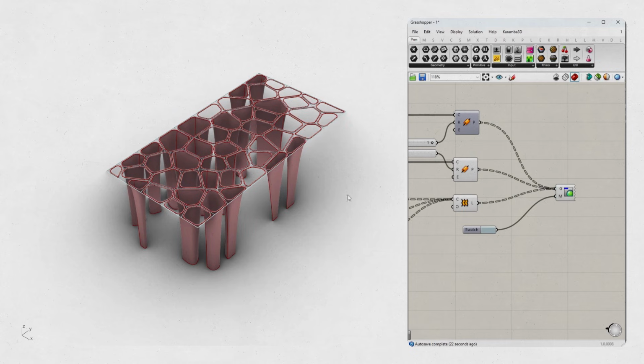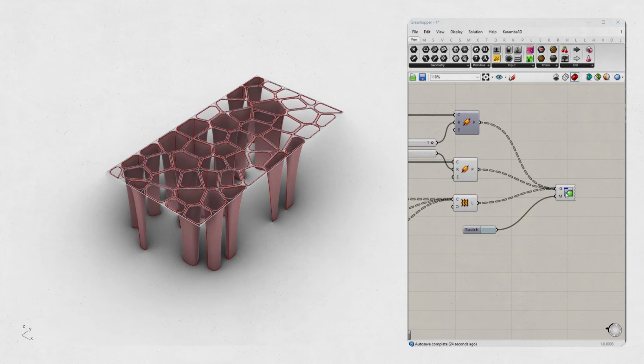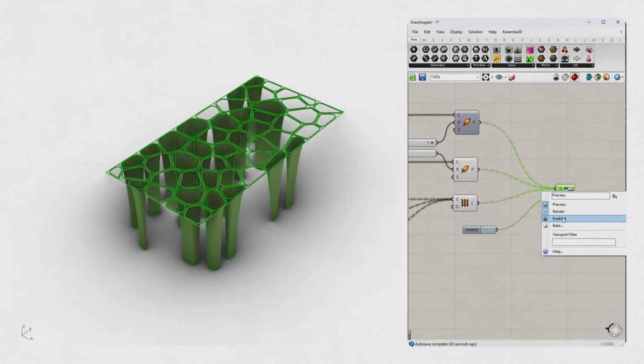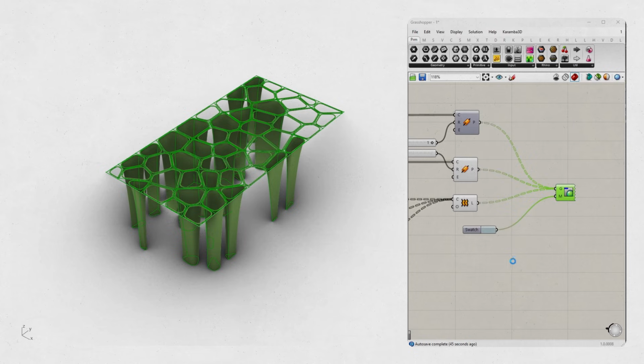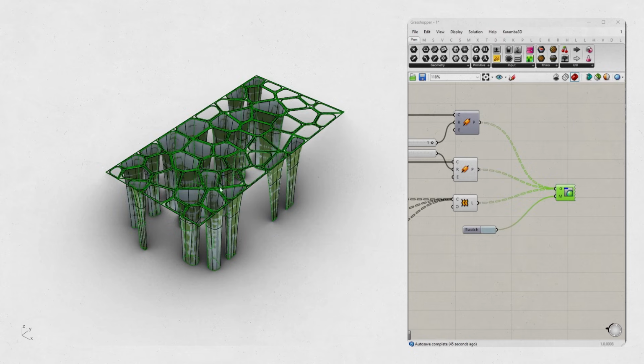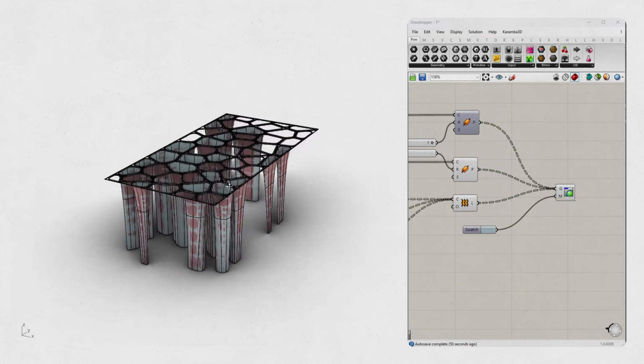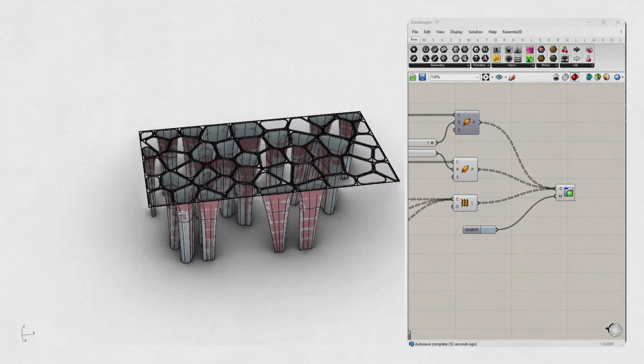If you want to convert your parametric geometry into actual geometry in Rhino, it's super simple. Check it out. One, just right-click on the component that's producing the geometry. Easy peasy. Two, then you pick the bake option. Got it? Three, Rhino's going to ask you where you want the geometry to be created, like which layer. Just choose your layer. Four, and boom. Now your output pops in as a standalone object in the Rhino space.